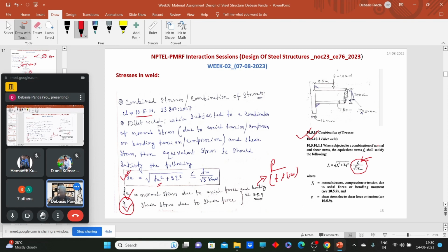Okay, so here we can see an example. Here this pipe is welded with this gusset, where this welding portion is done, and one point load and one twisting moment are applied. Due to this force, one direct shear stress will develop, yes or no? Let's name it Q1.